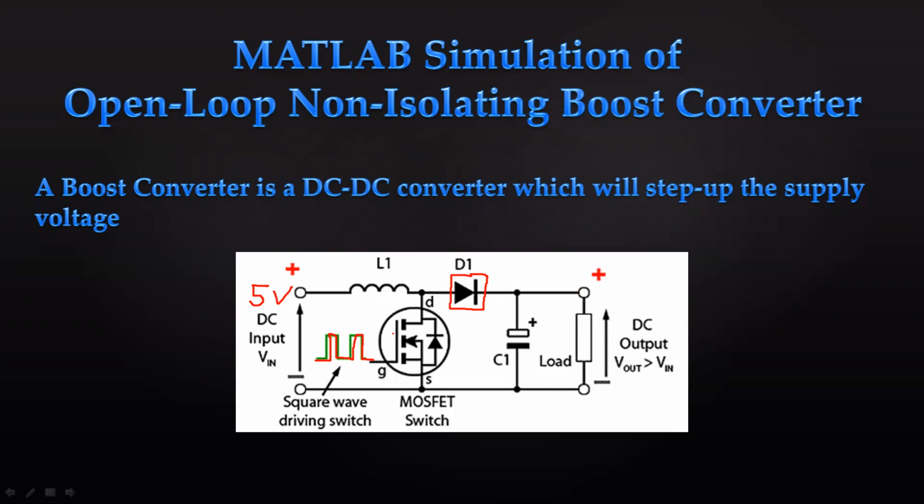So first, what will happen? This MOSFET switch has only two functions. First one is on, the second one is off, right? Let's start with the on function first. When this switch is on, this whole part is short circuited. Here we have 5 volts, so the current will pass through the L1 inductor and go back to the battery. This will charge the L1 inductor with the polarity plus and minus while charging.